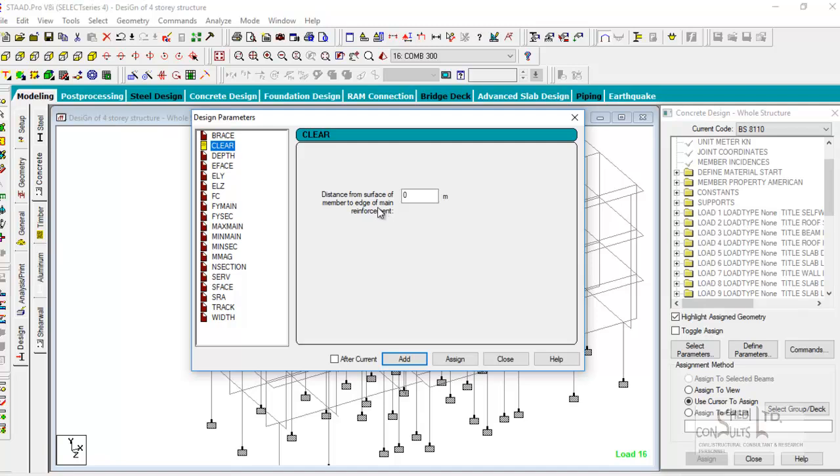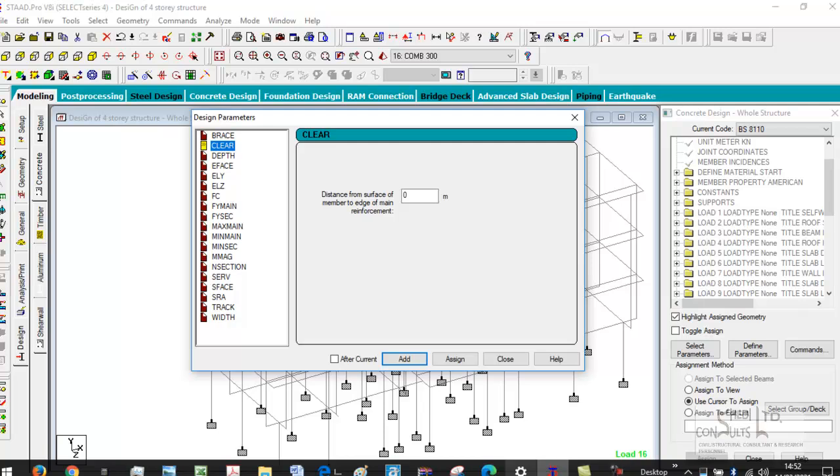So what you will do is simple. For your slab and the beams, we are using a cover to cater for 1 hour fire resistance in compliance with the code. The cover to our reinforcement, we are providing a cover of 25 millimeters. Then we intend to use a stirrup size of 10 millimeters. That means the distance should be 25 plus 10.